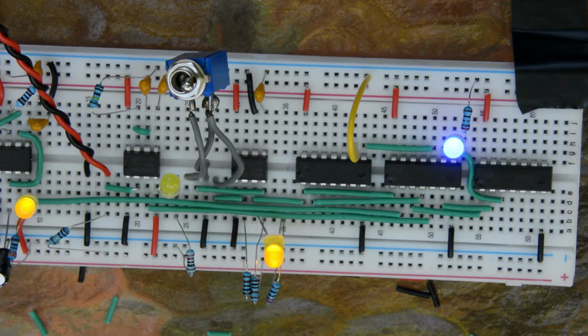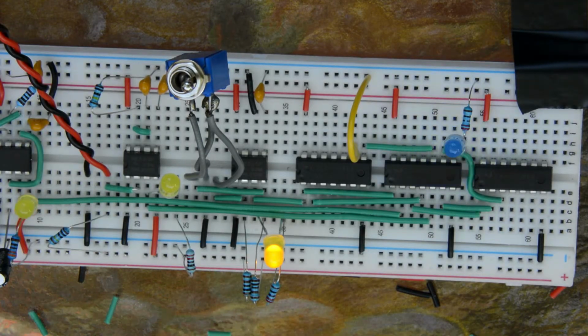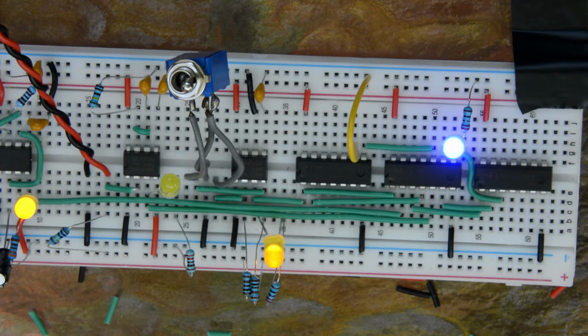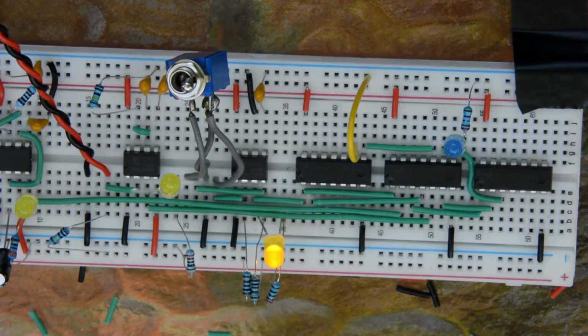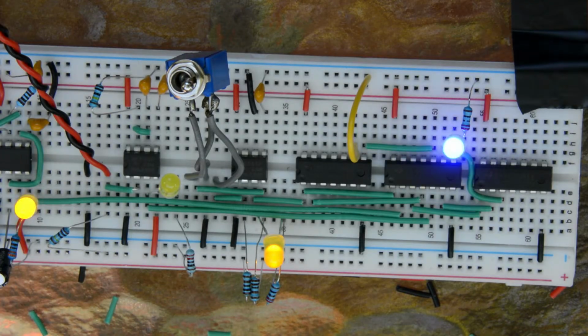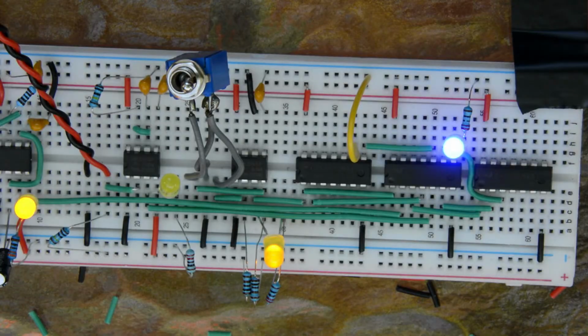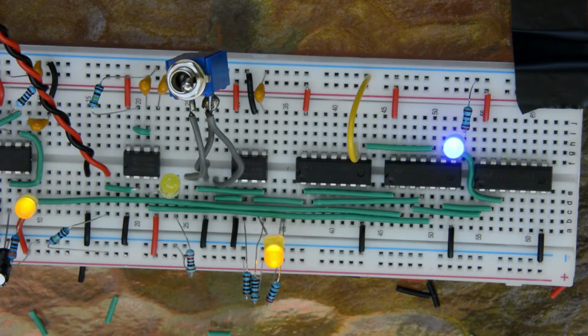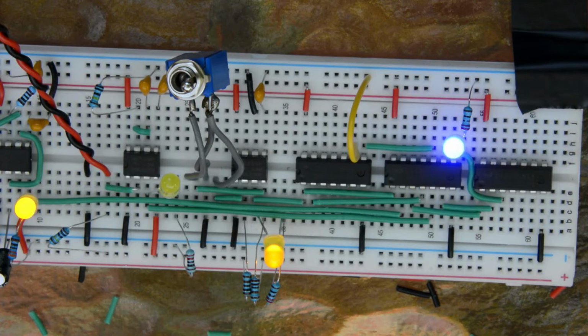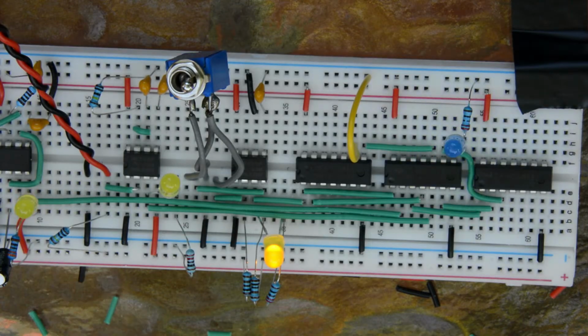Now the way that this astable configuration of the 555 works is that the 2 comparators inside of the 555 are used in a way that when a capacitor fills and discharges, it reaches the threshold in the voltage divider network inside here. It's kind of a complicated way to say it, but it's actually simple if you look at a block diagram of the 555 on Wikipedia. Okay, but then this other configuration is actually really simple.